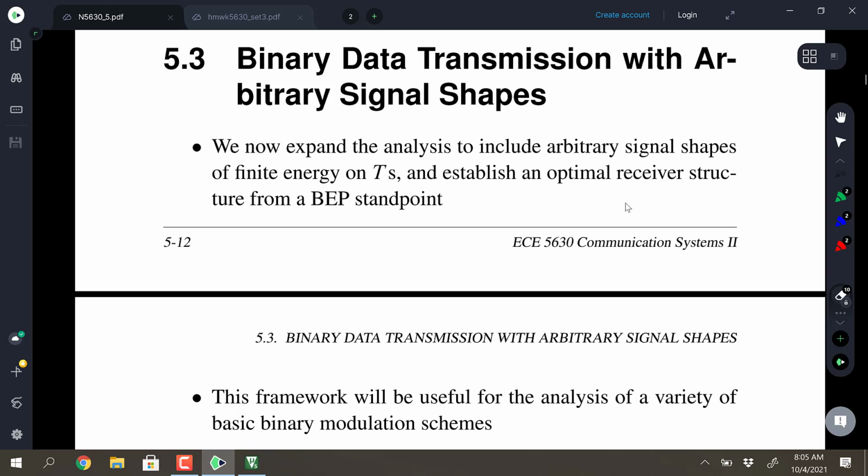We're going to start talking more about all of the other details that do matter, because pulse shape controls spectrum, pulse shape controls synchronization aspects. We won't get into synchronization until the next chapter, and pulse shape also controls performance on top of that, because signals generally don't go through a channel without suffering some impairment, like band limiting, let's say, and you're going to be experiencing that soon in a simulation model.